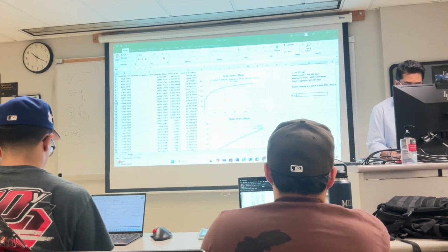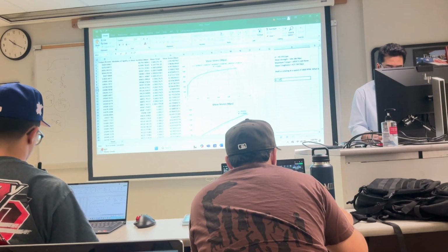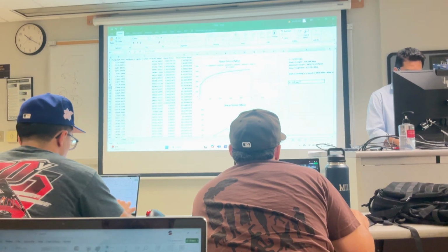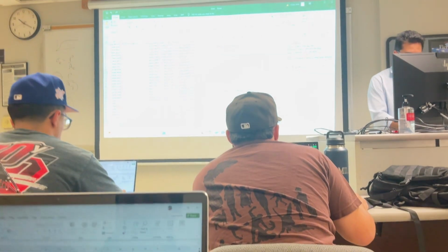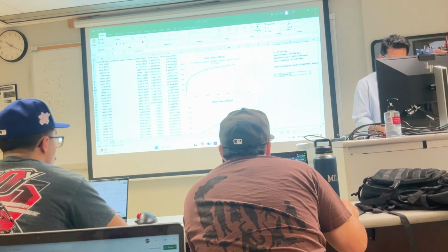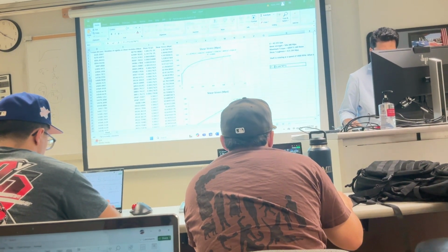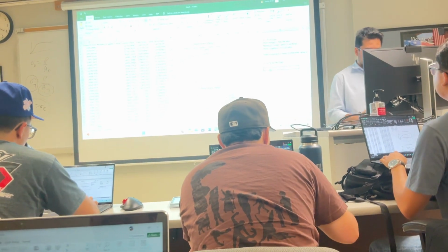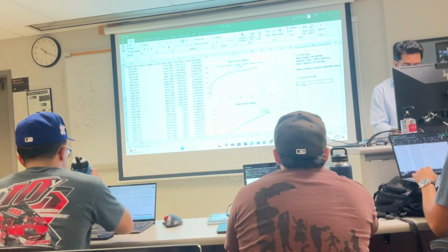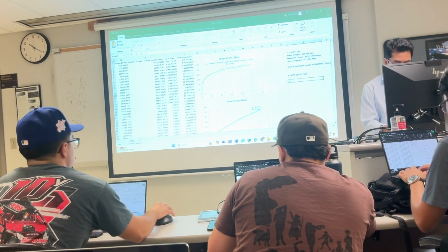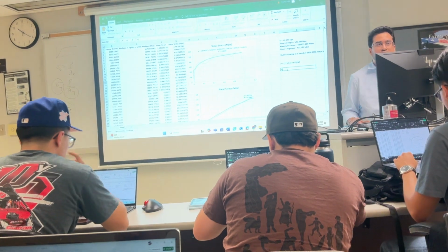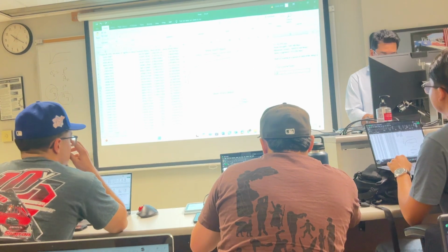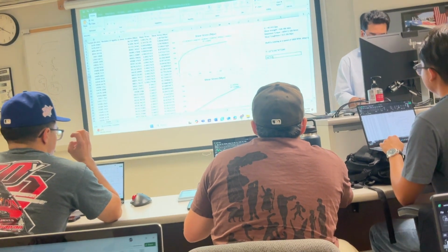What is the formula? Power equals 2 multiplied by pi, 3.141, times 1800, that is N, and then divided by 60. Do that. The answer is 188.5 radians per second. That is for 1800 RPM.